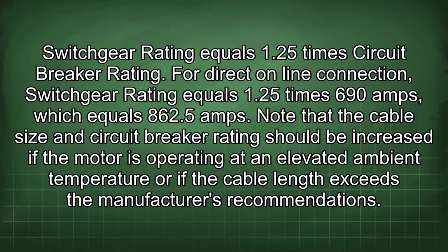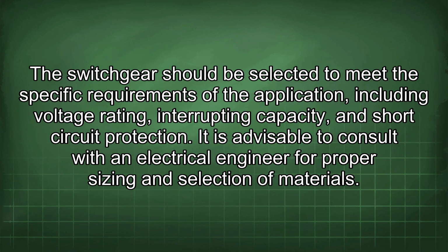Note that the cable size and circuit breaker rating should be increased if the motor is operating at an elevated ambient temperature or if the cable length exceeds the manufacturer's recommendations. The switchgear should be selected to meet the specific requirements of the application, including voltage rating, interrupting capacity, and short-circuit protection. It is advisable to consult with an electrical engineer for proper sizing and selection of materials.